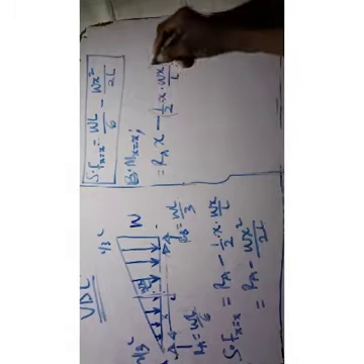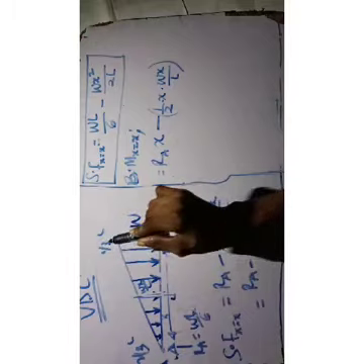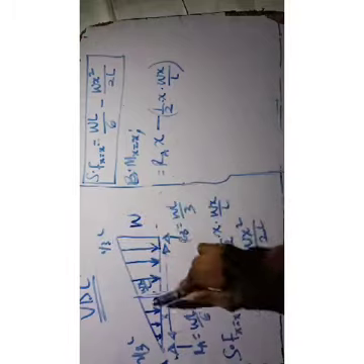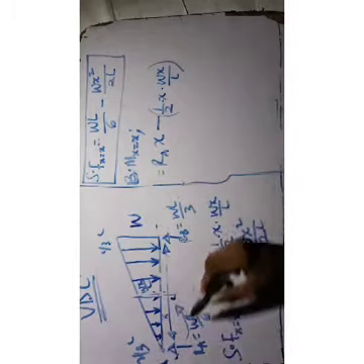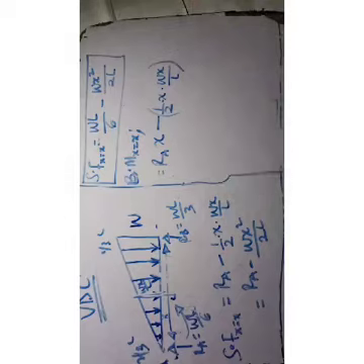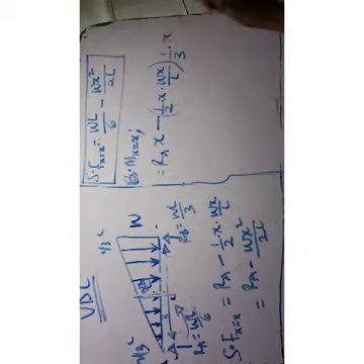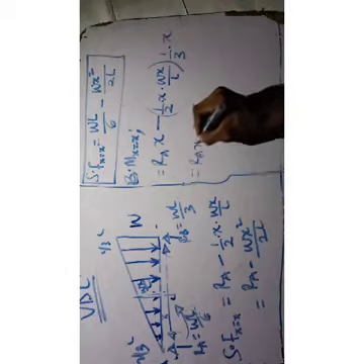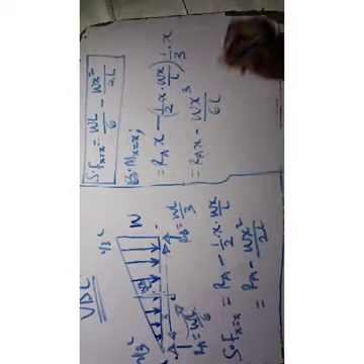This is converting to a point load. Then if you convert to a point load, don't forget, taking moments from the higher part, it will always cover 2/3, but you are going to make use of the 1/3, because you are taking the moment like this. So you are taking a line covering 1/3 of that length, and that will be multiplied by 1/3 of the length, which is X. And you have RAX minus, this is WX cube over 6L.